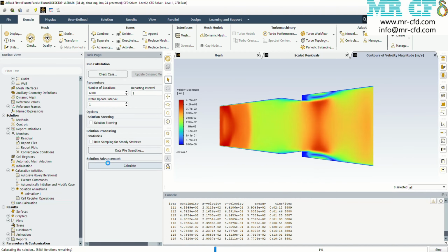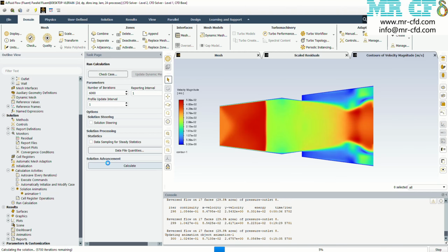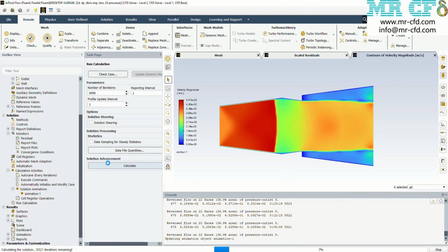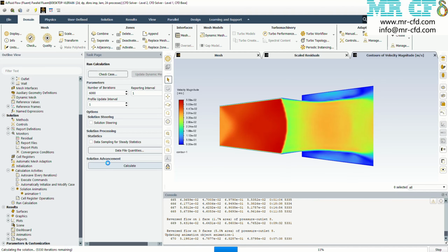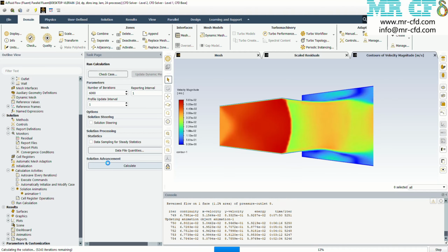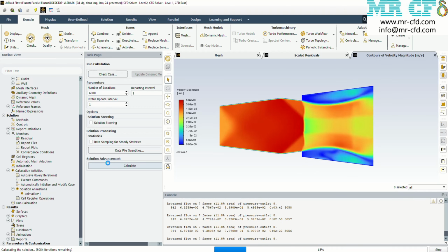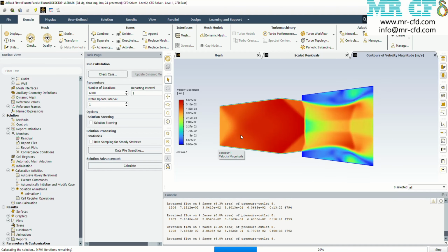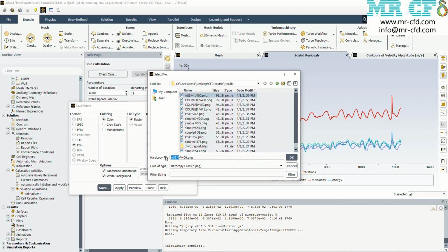In the last scheme, Roe, initially a normal shock generates at the channel's entrance and moves forward to the end. As with the AUSM model, after the normal shock reaches the corners, oblique shocks appear. And finally, these two shocks form a normal shock in the channel's center, completing the final shock system. However, there is instability in the shear flow region not seen in the AUSM model.